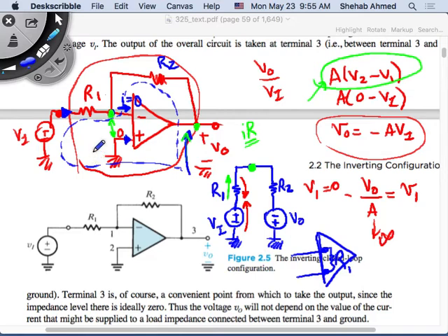But Kirchhoff voltage law does not say you cannot use this voltage between these two nodes to calculate this current. There's nothing wrong with that. This is a loop where I have an input voltage here, I have a resistor here, I have a voltage on the other side of the resistor. What's the voltage? It equals 0. Why? Because of the feedback. So this is what the feedback bought us. It allowed us to easily calculate the current coming into the op-amp, even though the current is not going to flow from the source into this ground, because this is not a physical connection.